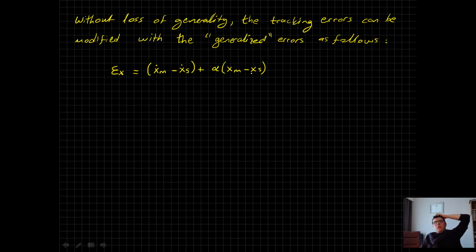Assume that we had only a position control problem, and as in position control, you can write here it's the reference minus response, right? And remember that we were able to modify this with a more generalized error defined that way. So we were including the derivative of the error function itself with certain linear scales.